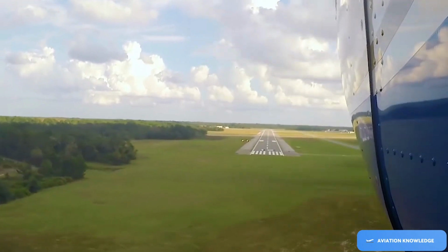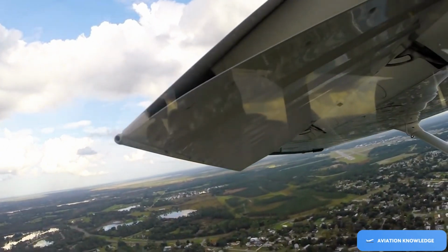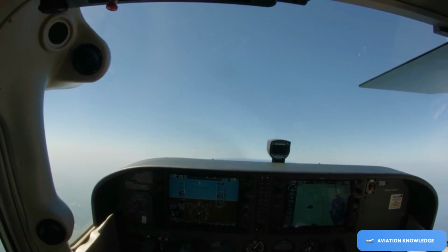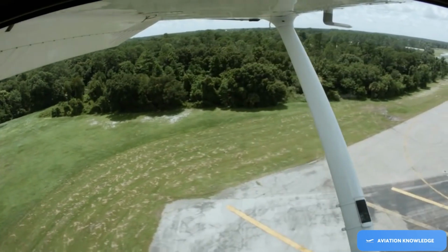Once you're on final approach and a safe landing is assured, set the flaps to 30 degrees and adjust your airspeed to 61 knots plus half the gust factor. At this point, the airplane will be operating behind the power curve, so it is important to maintain a stabilized approach. Make all of your callouts as you would for any other landing. Runway 23 verified. Stay around.